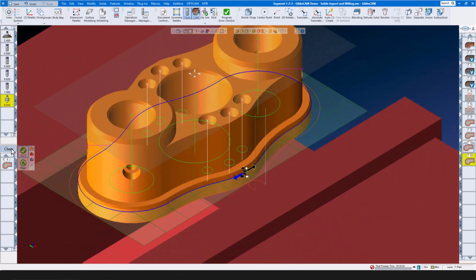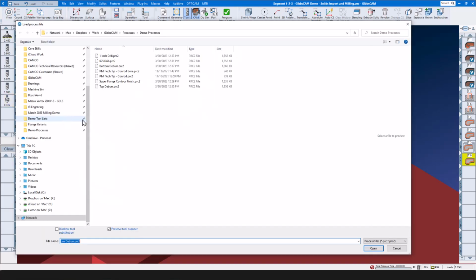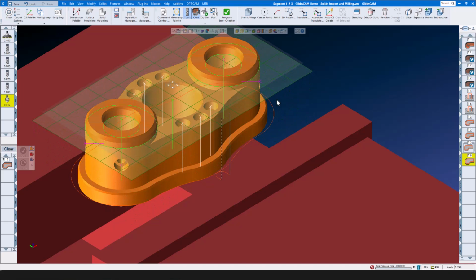It's time for the second deburring process, which has a different height and a different width. We save that one as well. Let's go back into the folder. We have bottom deburr. We also have top deburr. Once we import top deburr, it will populate the process list, and we can drag the profiler up into the bosses, select the two bosses with our control key, and click Do It.